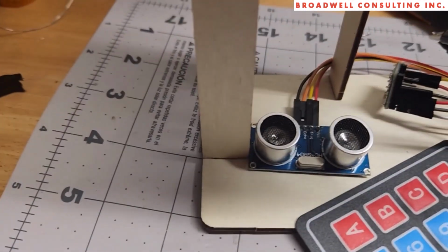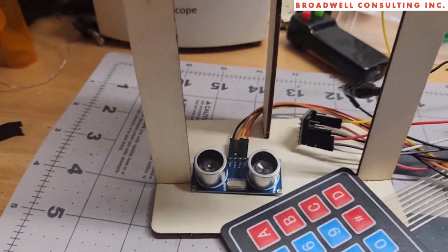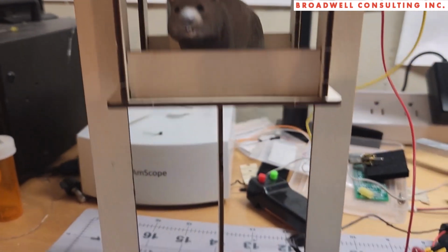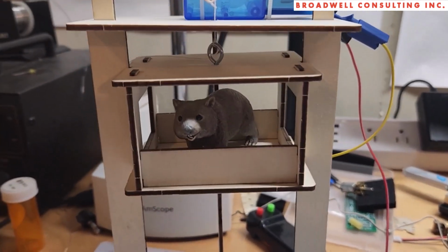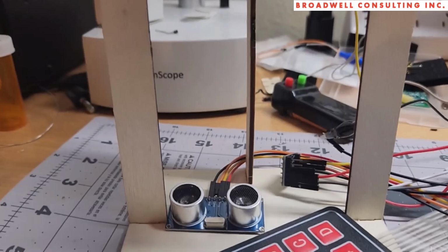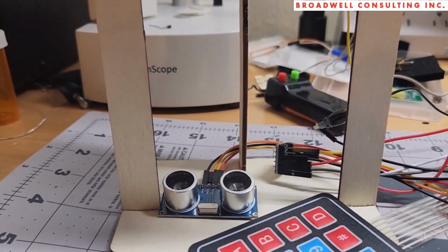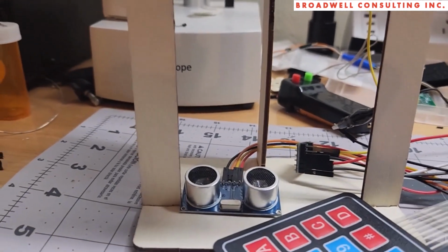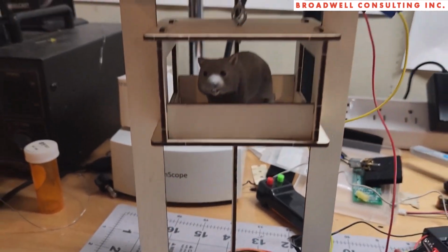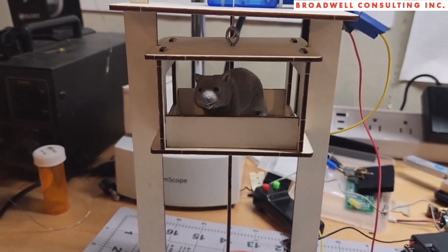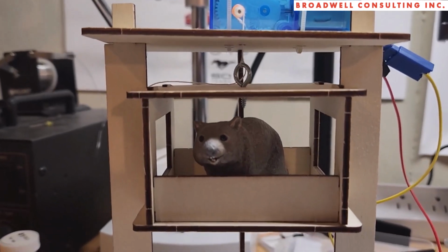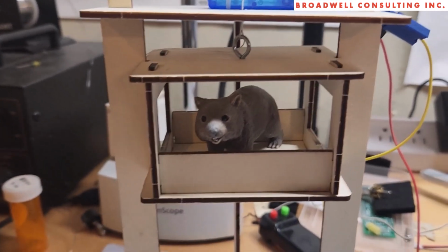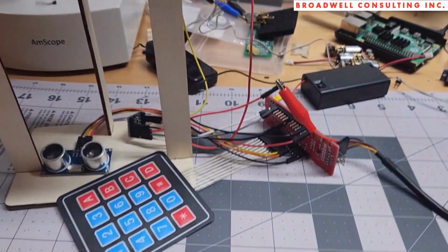We've got an HC-SR04 Ultrasonic Distance Sensor, which will sense the distance from the sensor to the bottom of the elevator car. There's a limit on that sensor of around 4 centimeters, so we won't be able to come all the way down till we touch it. It needs a little bit of distance to do the ultrasonic sensor measuring. We're limited on the top by the string and the eye bolt. We don't want that to hit the top of the elevator shaft.